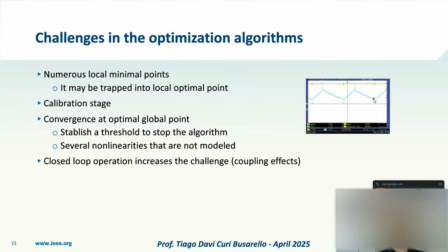Since you have two environments, the physical and the virtual, the controllers are also identical, and then any modification in the parameters, the controller understands as a disturbance and tries to compensate. So the interaction between the closed loop controller and the parameters variation is quite challenging.